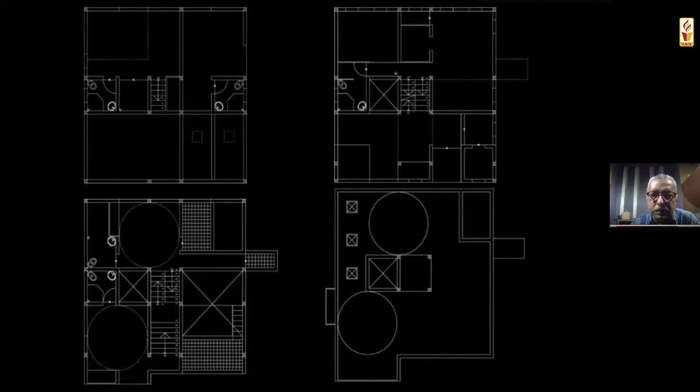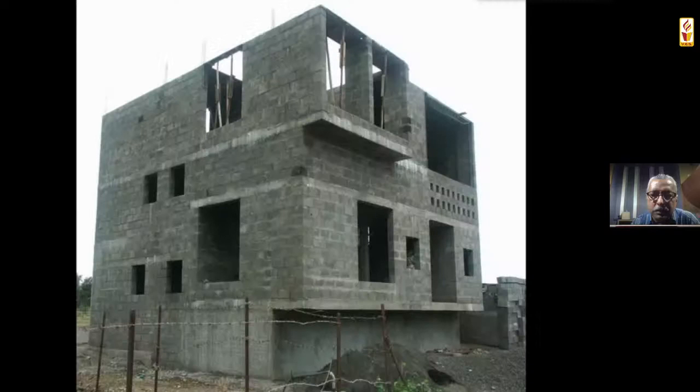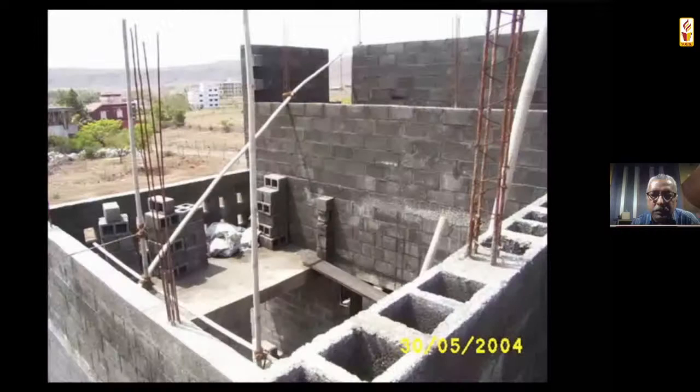Many levels. The specialty of pillar slab is that you can do work at many levels. And then this is how the building looks from outside. At this point of time, you have a choice of plastering it or not plastering it. In this particular one, we did double plaster because we didn't have budget. So instead of double coat plaster, we had just a single coat. But this is a building halfway.